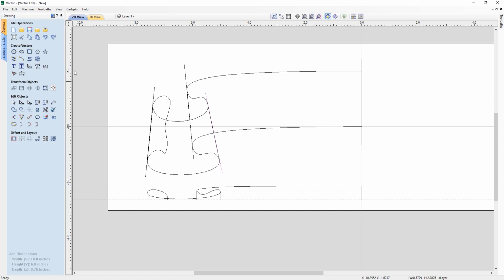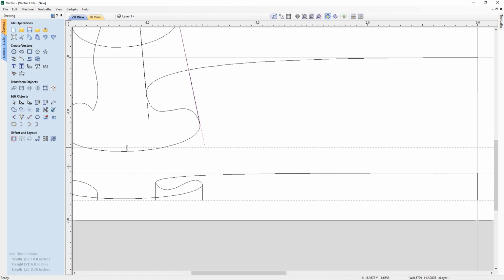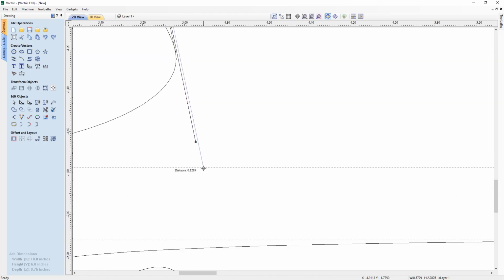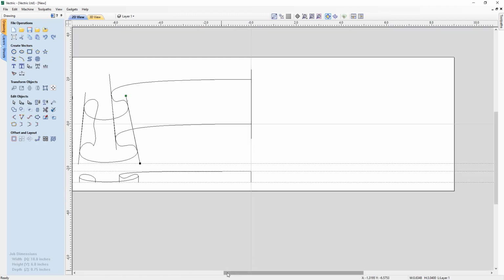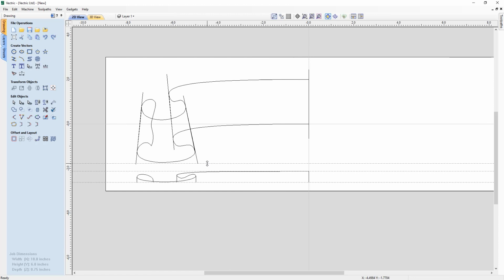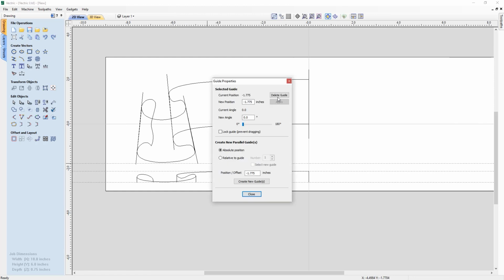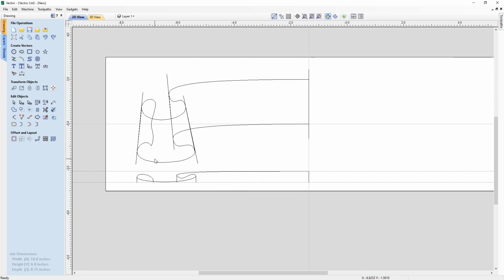And if you're not quite sure whether they line up or not, then just go back to your selection mode and drag out a guideline. And just make sure that they miss the bottom of this, because if we end up extruding so that we don't get our full shape in there, we're going to crop it off prematurely, and we don't want that. So you'll see that that's not quite long enough. So let's use this guideline and drag it down. Go into our node mode again, and we can pull this out so that it's proper length for what we need. So we don't want this guideline anymore. We can hover over it, right click, and say delete guideline.